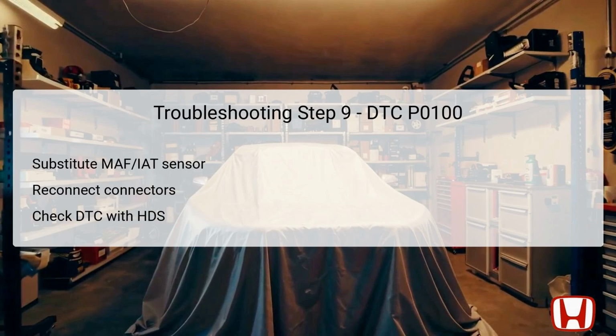In the final step of troubleshooting for DTC P0100, it is important to conduct a thorough check of the MAF sensor, IAT sensor. Start by turning the vehicle to the off position, then substitute a known good MAF IAT sensor for testing. This will eliminate the possibility that the sensor itself is faulty, which is common when error codes are displayed. Once you have the new sensor, reconnect all the necessary connectors securely to ensure proper functioning.